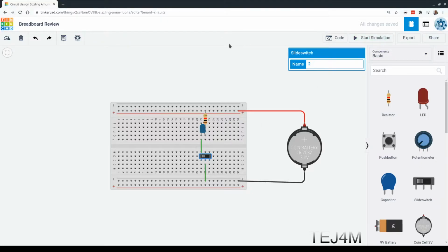However, there's more to this switch. You can use the right terminal as well. So this is known as a 2-pole switch, meaning that it can, is it a 2-pole switch? Let me just look that terminology up for a moment. So yes, it's called a 2-pole switch because it can control 2 separate circuits, one on the left and one on the right. The terminal in the middle, where it says common, is going to ground.